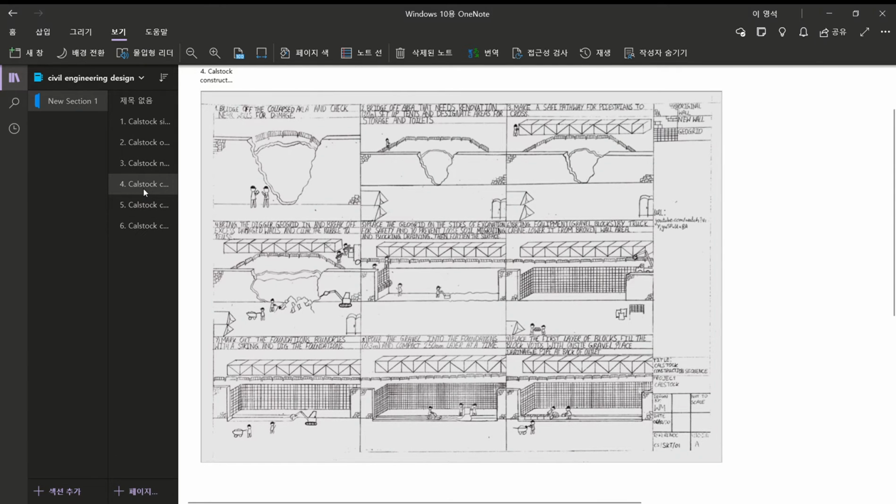First, construction workers will barrier off the collapsed area with fences so that people don't walk near it, for their safety. Then they will check the walls next to the collapsed area to see if they are damaged and need to be repaired as well. After surveying the wall, the whole area will need to be demolished and has to be barriered off. For the retaining wall, we decided to repair 10 meters from each side of the failed area.